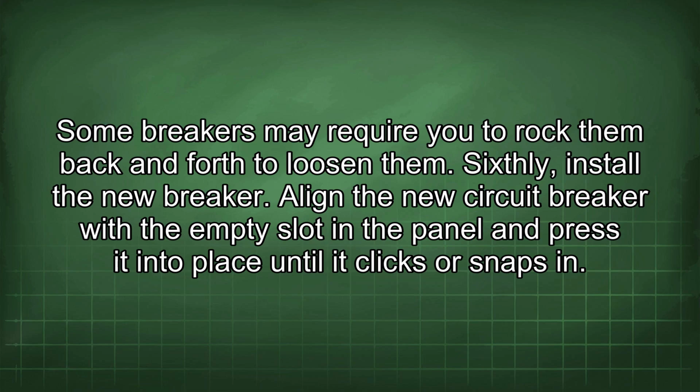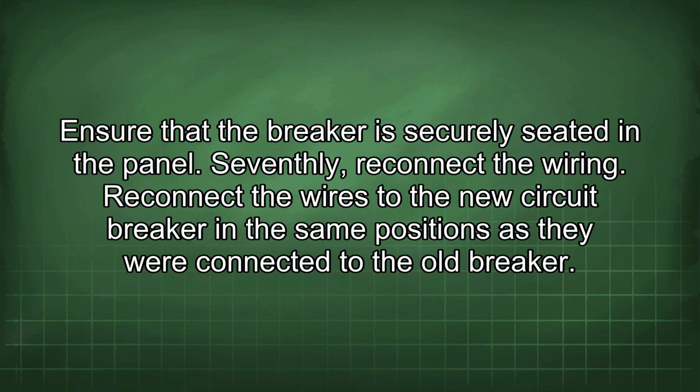Sixthly, install the new breaker. Align the new circuit breaker with the empty slot in the panel and press it into place until it clicks or snaps in. Ensure that the breaker is securely seated in the panel.